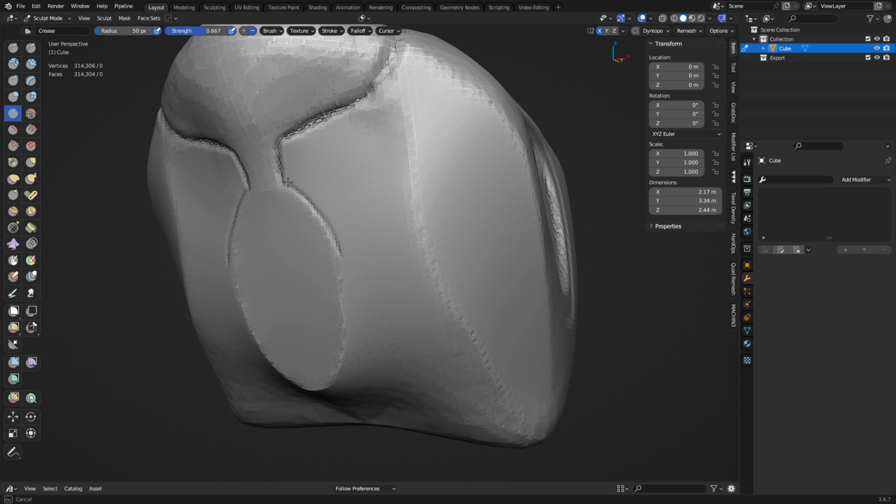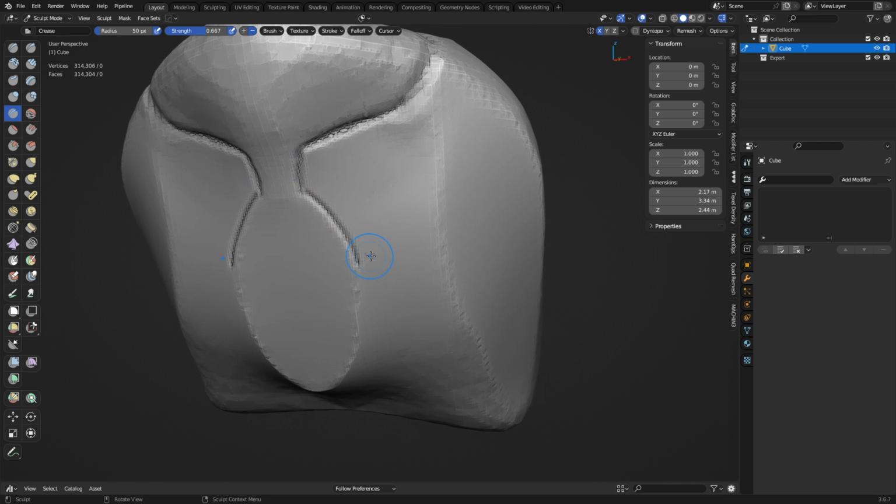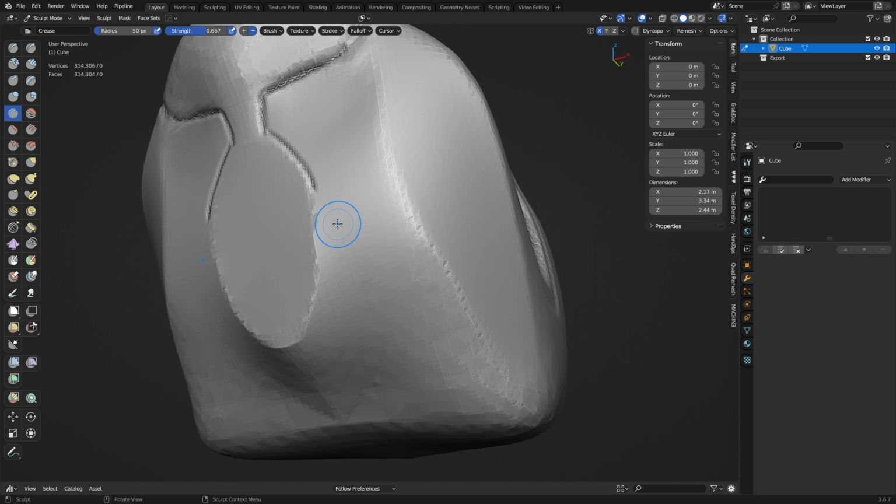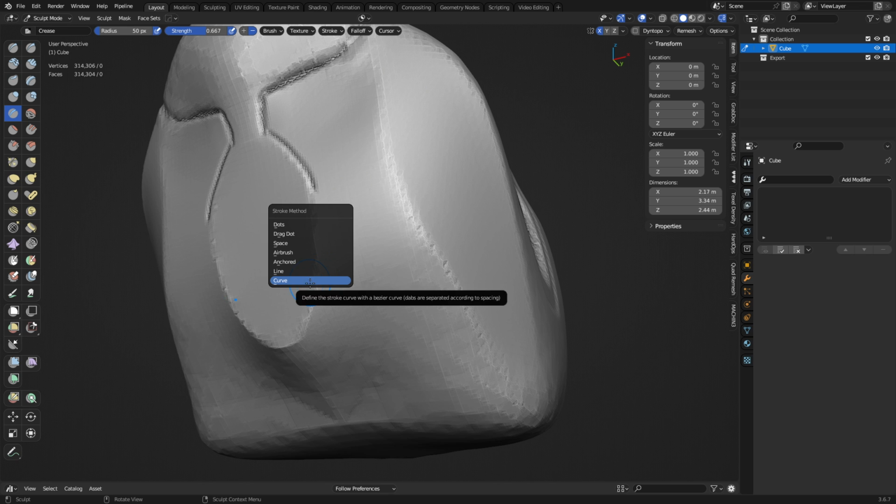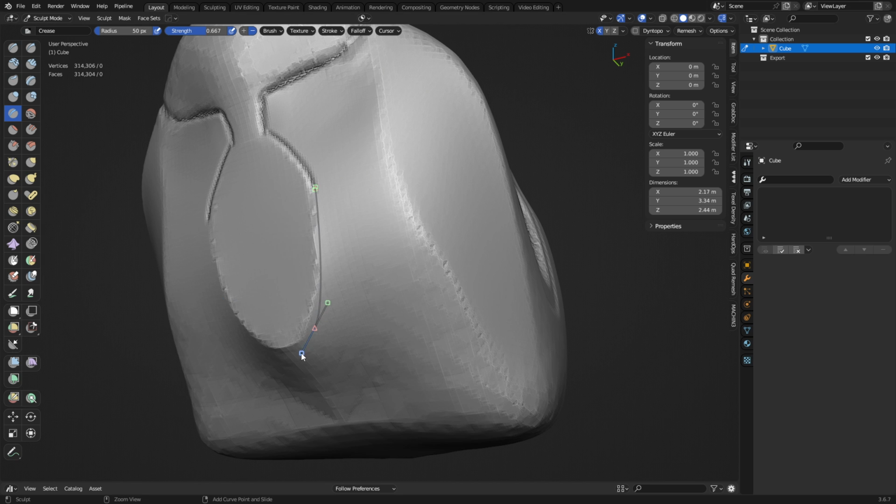There's definitely different kinds of brush strokes, like using, for example, let's say in Blender 3.6, you would press E. I think it's Control E in Blender to bring up the stroke menu, but the curve tool, right, for example. And this one's pretty simple. You hold Control and right click, and you can set up some curves like this, and it's view dependent, so you don't want to rotate your view, but then you would just hit enter and boom, you can set up a stroke like such. Pretty simple and straightforward, right?